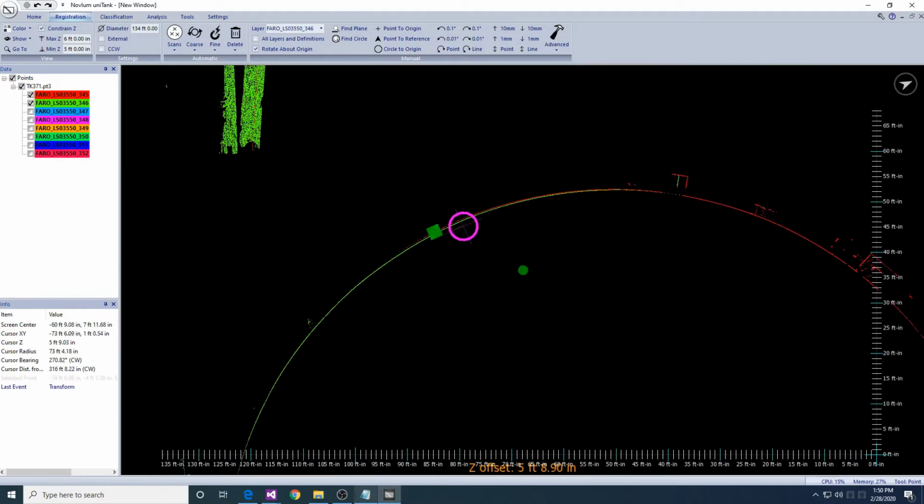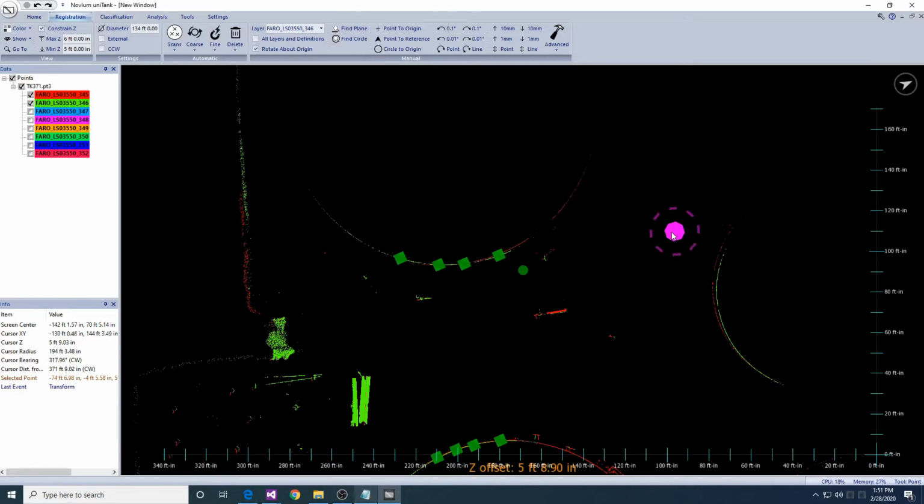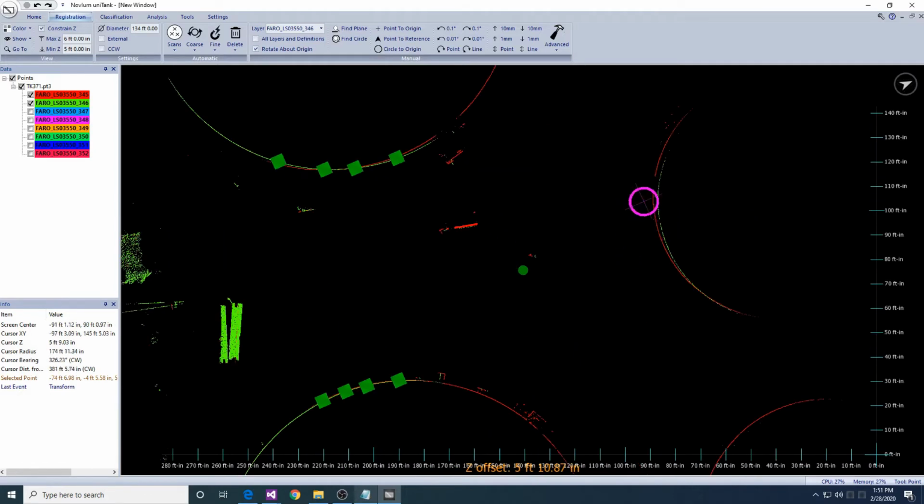At first, I will only register the horizontal translation and rotations. I use only vertical features and avoid using the berm because I know that the vertical translation of the layers has not yet been adjusted.